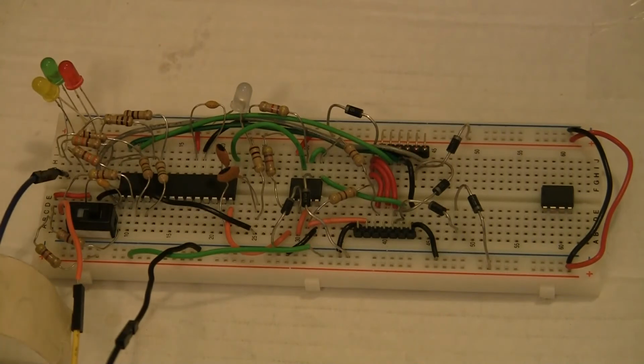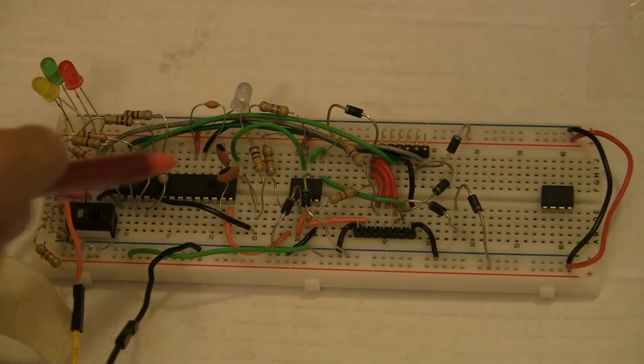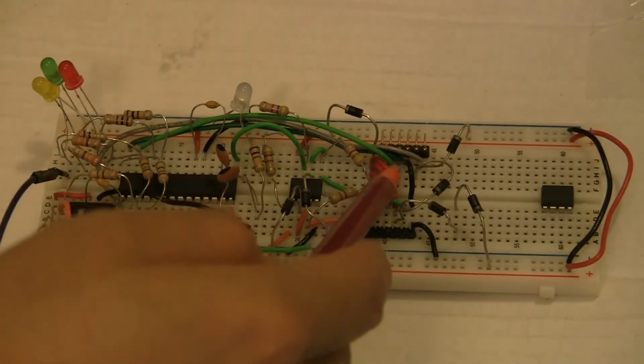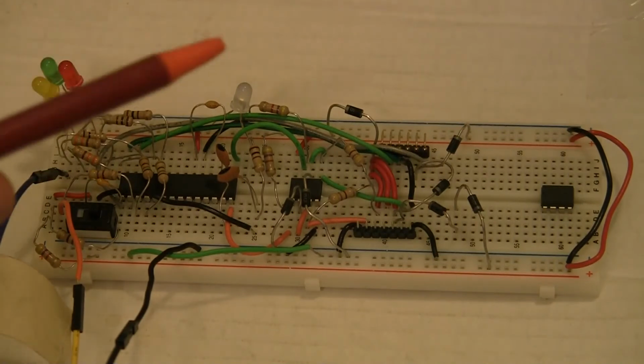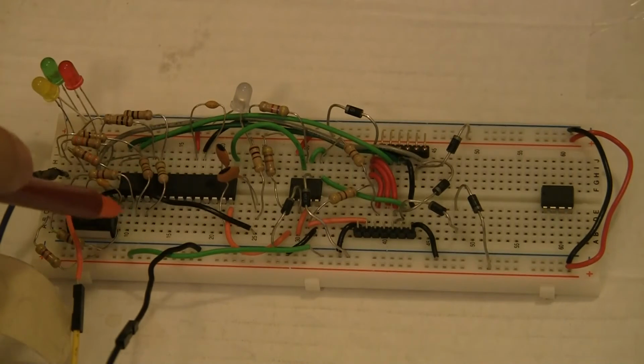The approach I took was first just to get the PIC on the board, get the ports for programming with the PIC at 2 or 3, attach some debugging lights over here in red, yellow, green, get some basic resistors, and make sure that I can read ADC values correctly first.